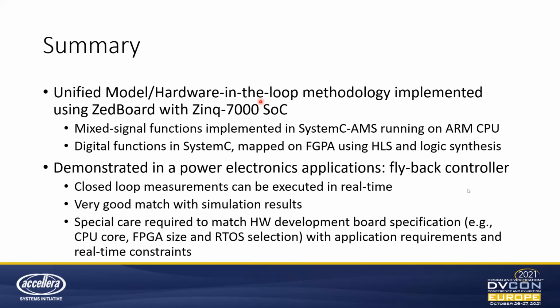Yes, the limitation is not the data rate, it's the turnaround time. The data rate can be quite high for the interfaces, but the turnaround time is limiting the whole closed loop application. In this case, we achieved around 120 microseconds with the CPU load. If the SystemC process gets heavier, then the loop time also increases. But if the model gets smaller, then it also gets faster.